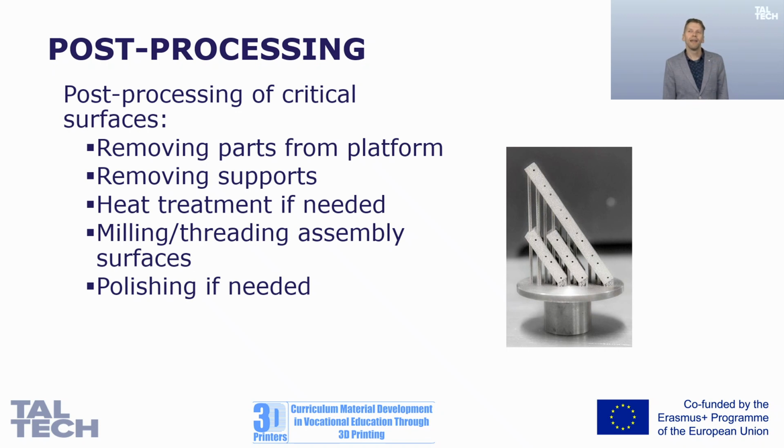Because of the high temperatures during the process, in most cases we have to use supports to attach the parts to the base plate. So when we are using supports, it means that we have to remove them. But as metals are quite strong, removing the supports can be challenging. So we have to use cutting tools to do it.